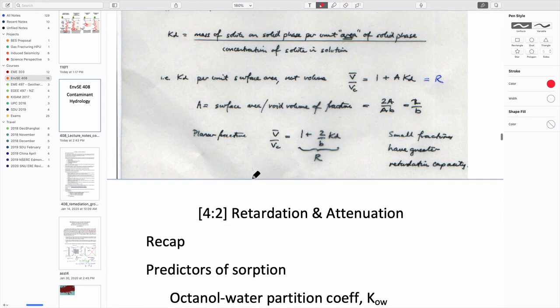And that's it. And so we've made the case for the fact that we have non-conservative transport. We summarized what the advection dispersion equation means if it's conservative. We added an extra term on the end that allows for stuff to be removed from the liquid part and put onto the solid. We can define that in terms of isotherms that we can call linear isotherms and a distribution coefficient, which is probably adequate for what we want to do.